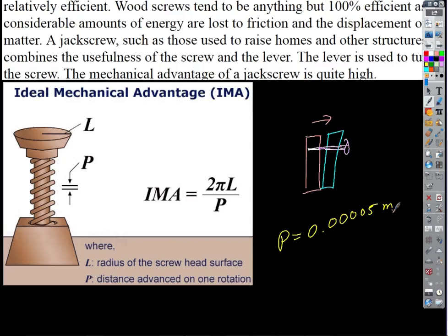We don't know how powerful the motor is though. But 483 to 1, yikes. Even if your motor's pretty weak, you could pick up a ton of stuff, but you have to worry about the structural integrity. It's just aluminum. Aluminum, you'd want titanium, or moly steel, hardened steel, or something.